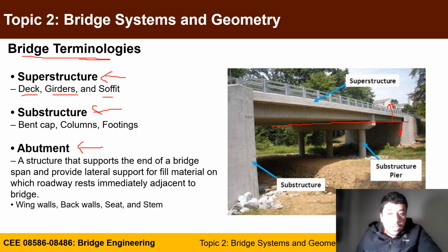If you can see here, we have footing for this frame. This frame, we usually call it bent. So the footing is embedded in the soil. We have the footing, we have the column bents, and the columns are joined by a beam. We call it bent cap, and this frame is one support of the superstructure.